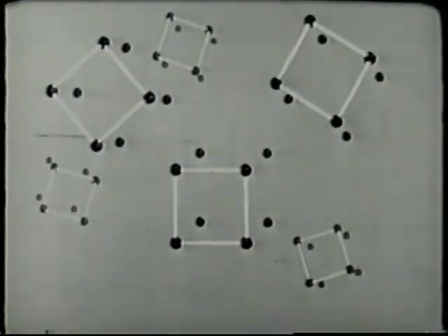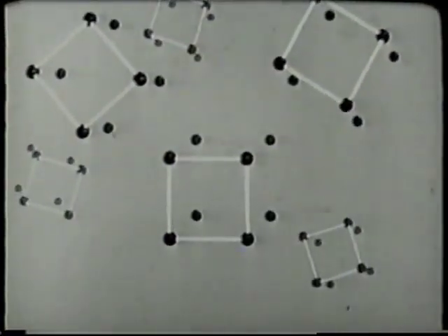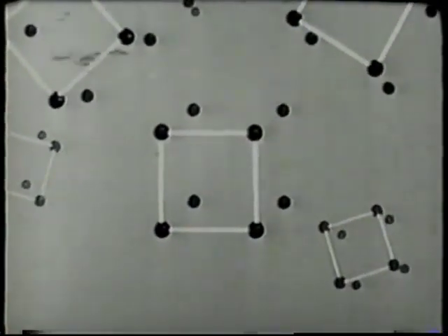An understanding of the aluminum alloy's crystal grain structure, shown in this photomicrograph, is essential to an understanding of the heat treatment process and its accompanying property changes. Crystallization occurs in the initial production or casting of aluminum and aluminum alloys and is the physical root of the metal's characteristics. As the molten metal is cooled to its freezing point, groups of atoms join together at various points throughout the liquid to form small individual lattices or unit cells of solid material.